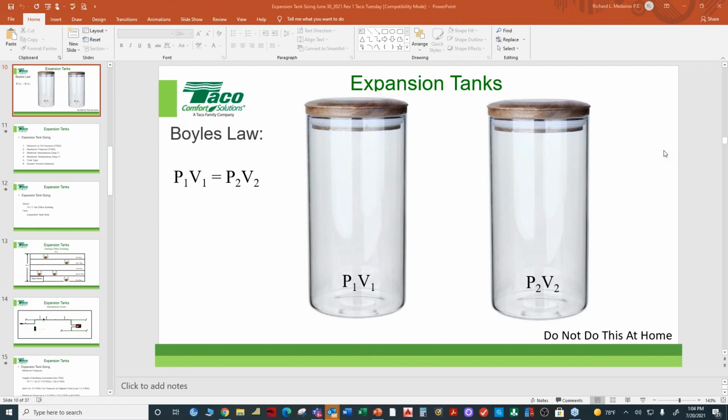Great question, John. If you undersize an expansion tank, then you will exceed the maximum pressure that your system was initially designed to handle. So in our case, if instead of putting in a 100-gallon tank we put in, say, a 75-gallon tank, then it would exceed the 110 pounds per square inch gauge maximum operating pressure. If that was high enough, it could potentially set off the relief valve. If there was a malfunctioning relief valve and no place for the water to go, it would damage equipment in the system. So undersizing has major consequences. Oversizing does not.